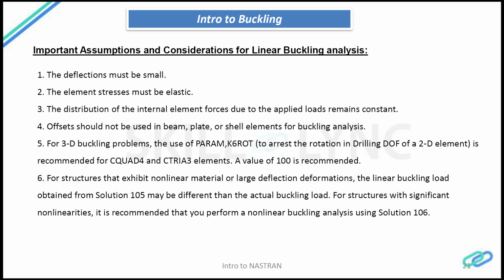The first consideration is that the deflection must be small. You can ask me, how do we quantify small? As a general thumb rule within the engineering community, they take the thickness of the component divided by 10, the T by 10 ratio. Whatever deflection you get should be less than the T by 10 ratio.